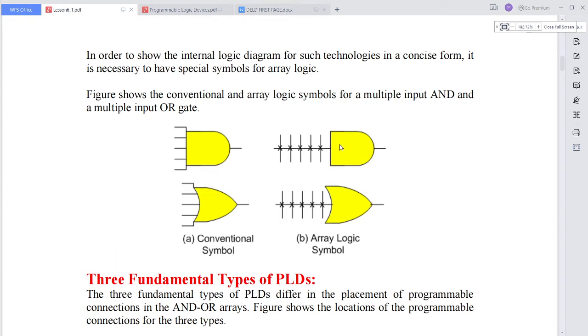But in the case of a conventional gate, irrespective of that, every time we need to apply the input signals to get that particular output. Here, for example, assume it has 3 inputs, so it will verify all 2 power 3, that is 8 combinations, 000 to 111.